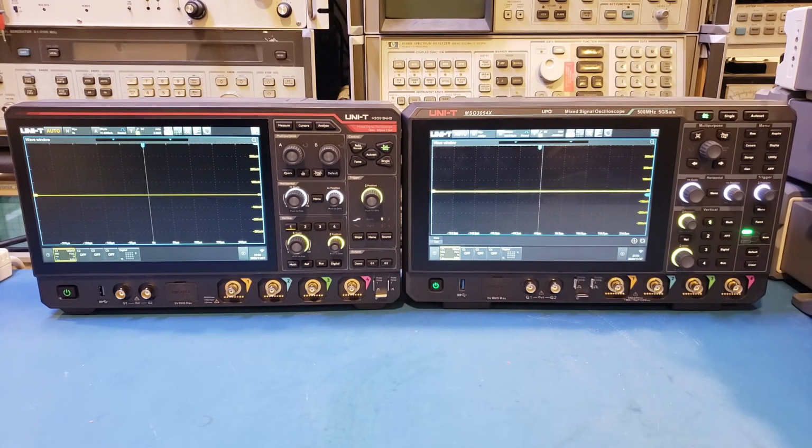By the way, the MSO5104HD also has the enhanced resolution mode, or ERES mode, which can further enhance the vertical resolution up to an additional 4 bits. This gives you a maximum enhanced resolution of 16 bits. Now, this is actually achieved through post-processing, as the ADC is only capable of digitizing 12 bits. As a result, the trade-off of the ERES mode is that the oscilloscope bandwidth is greatly reduced. So let me actually show you that.